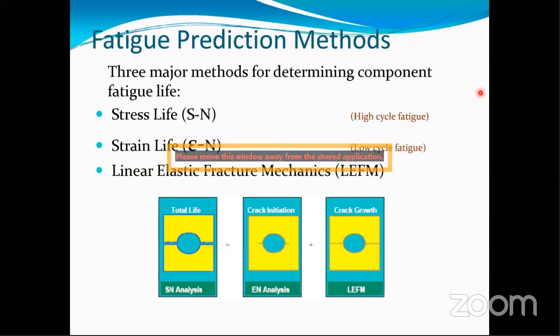So stress will become the important factor to be taken as a fatigue prediction criteria. But in case of strain life approach, the strain will be very, very high, so the component fails below say 10 power 3 cycles or so, like 1000 to 10,000 cycles or so.